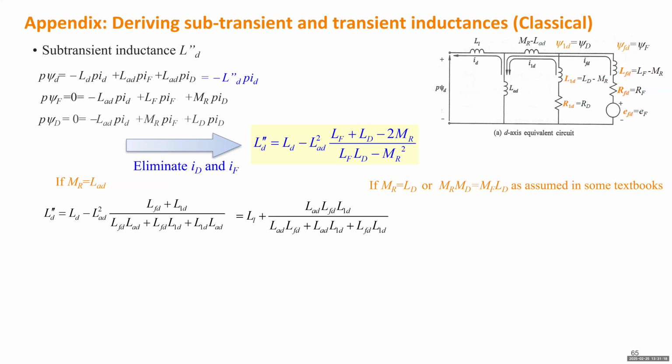But if you make this one, you will see another different formula, which is this one. So why do they like this formula? Because all the inductances in dq with single and double prime will follow exactly the same pattern. That's why they like it. Later, when we derive the circuit, this one is more convenient. That makes the model simpler. So later we might try this one, but I'm just explaining.